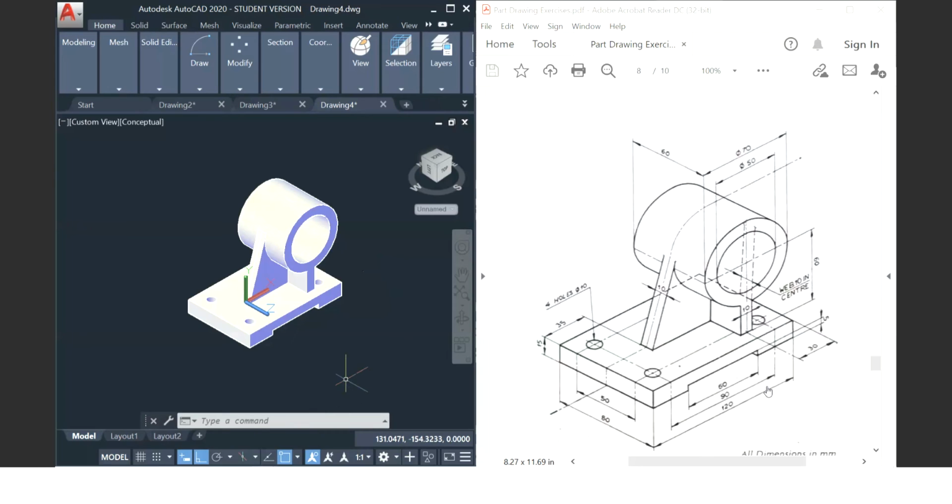Okay. So please remember, when you want to do whatever geometry drawing that you want to construct in here, the most important part is you need to choose which plane that you want to construct that geometrical drawing, and make sure that plane is going to be your XY plane.